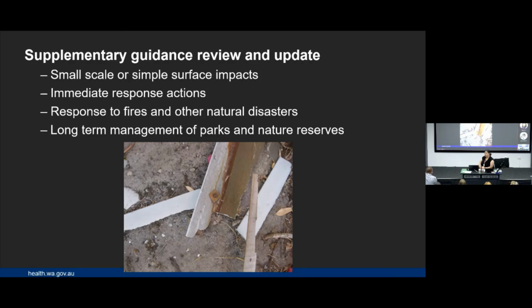Yeah, so with public health risk, it's about air sampling. If you want to start judging whether there's an immediate risk to public health, you can use air sampling data to assist you to see if there's any material in air, and you have to consider air sampling under the conditions that the site is being used and where there may be a risk. So that's where your conceptual site model becomes really important. What are your receptors? What are the activities happening? What are the jobs that are happening?